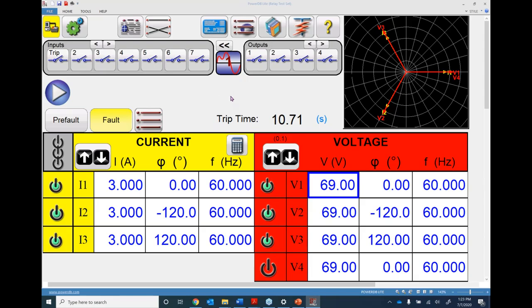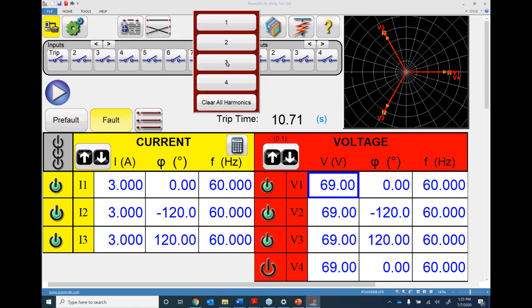One of the distinctive features in RTMS software is the harmonic waveform generator. In the harmonic waveform generation, you can generate multiple waveforms on each particular channel here. When you work on applications like harmonic restraint test for electromechanical differential, or any type of transformer differential relays, or if you need to use a certain type of harmonic injection for the application you're testing, you can always use this feature. So if I go to the second